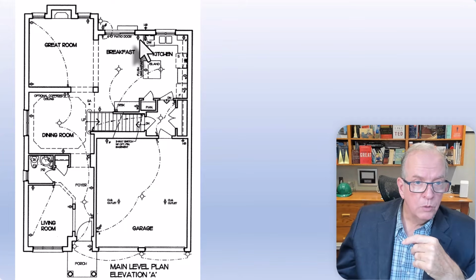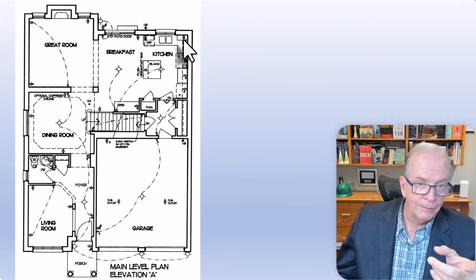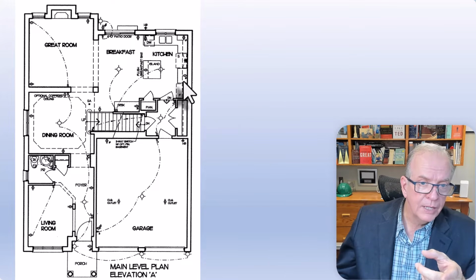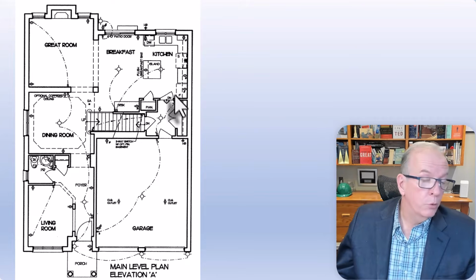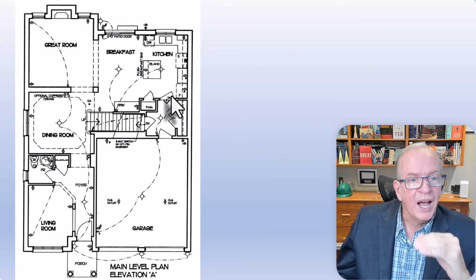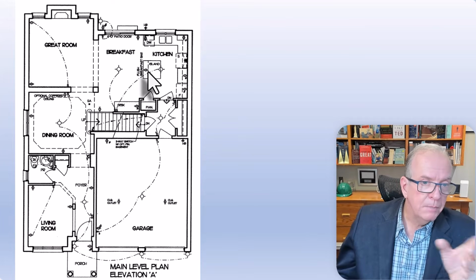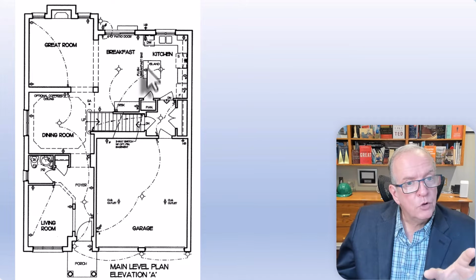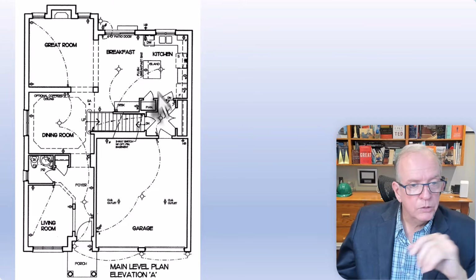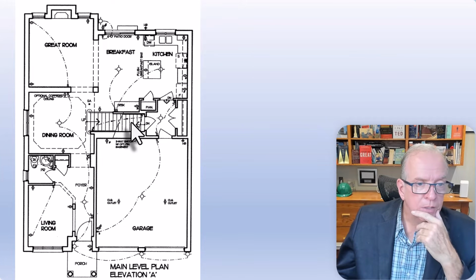This is showing you more outlets in the kitchen. There's a little number there. I'd have to zoom in, but it would tell me how high that outlet is. Basically, it's got to be high enough to be above the counter, right? So when I see this and there's a little bit of what looks like writing, if I zoomed in, it would tell me 42 inches above the floor as an example. So you'd want to make sure it's whatever height it says. This one's not telling me, but I know it's in an island. So if I'm an electrician, I'm going to be finding out. I want to see the shop drawings for the kitchen, and I want to know exactly where you want this outlet, right? So it's those kind of things that go on drawings.